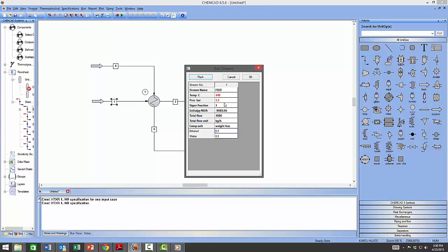The vapor pressure of 0 will indicate that the liquid stream is at a temperature equal or lower than the bubble point, with a temperature lower than the bubble point indicating that the stream is supercooled. And we have been told in our problem statement that the vapor stream is superheated. To what degree of superheating we do not know, and we can evaluate that in Chemcad.